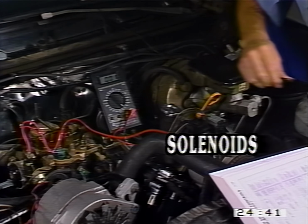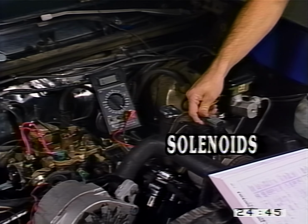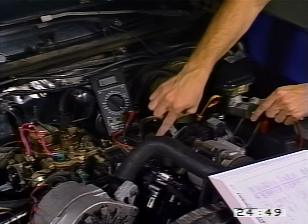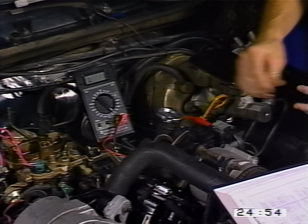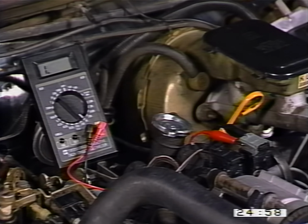Solenoids are checked by applying voltage and taking a look at their operation. Measurable resistance should be found across the windings, and they should neither be shorted to ground nor open. Either a shorted or low-resistance solenoid can damage the computer. Check all solenoids before replacing the computer.